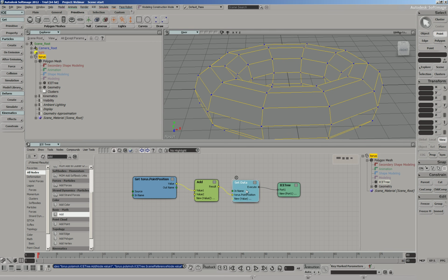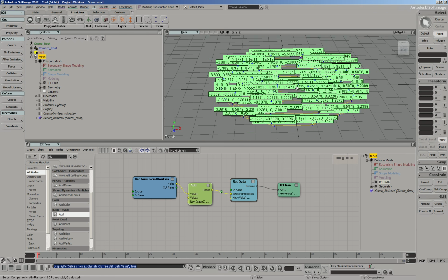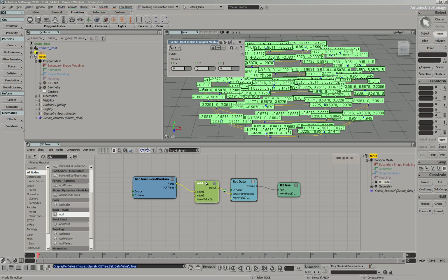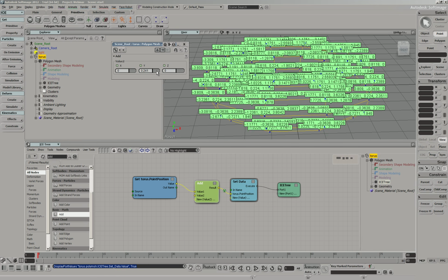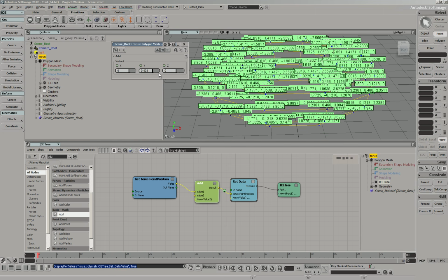That lets you know it's going to insert it like that, and you don't actually have to manually connect those together. Now if I right click on here and do a show values, there's all my values again, my vertice values. But watch this, if I double click on add, I can now add to every single one of these vertices the same value and say y, like that. And notice that all the middle values are changing as I scrub here.